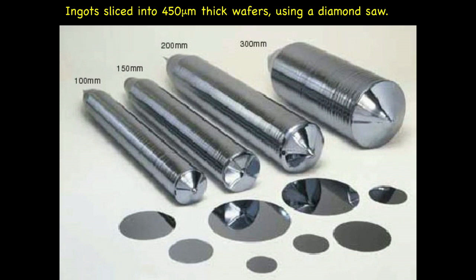The reason they grow over time is that the cost is kind of fixed with the time that it's in the factory, and all the steps are about the same, independent of what size the wafer is. So if you use bigger wafers, you can build more chips at once, and that kind of reduces the price per chip. But the machines that handle bigger wafers are different than the ones that handle smaller wafers, so the machines have kind of been getting upgraded over time.